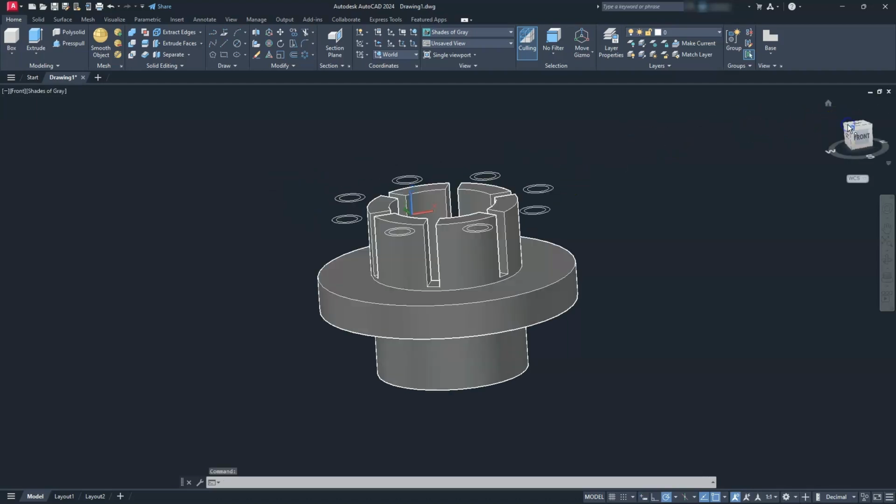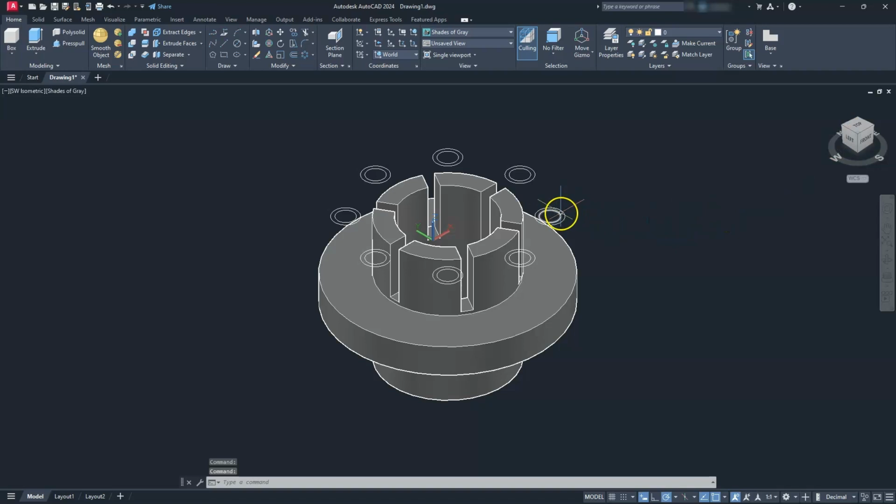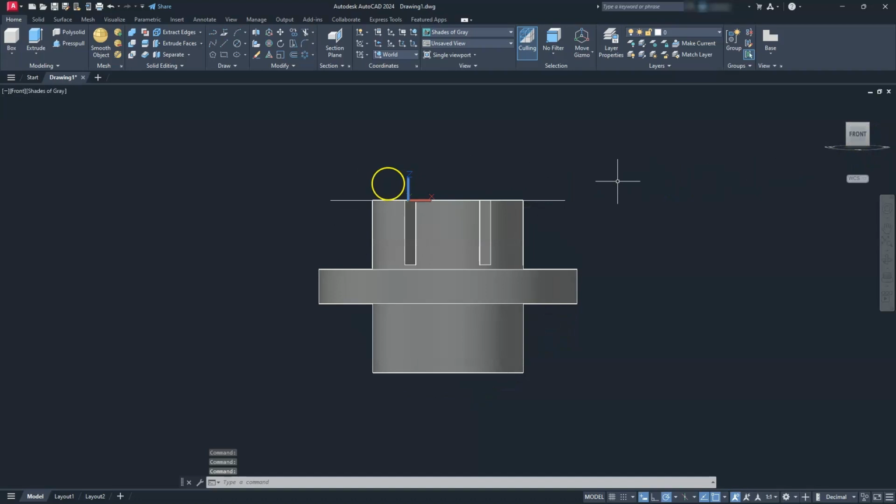What I mean by that is if I rotate back, I'm taking a look at all of these little shapes here. If I go to the front view, they're going to look like a line. But I need to pull these down a distance, right? So I'm going to select them first, using a blue window to go across them. I'll select this blue axis, and then pull downward, and I always go way past it just to exaggerate it a little bit. But I'm going to type in a distance of 30, because that's the height that I need that to go down from the top here. So once I type in 30, go ahead and hit enter. You will see that they are there.